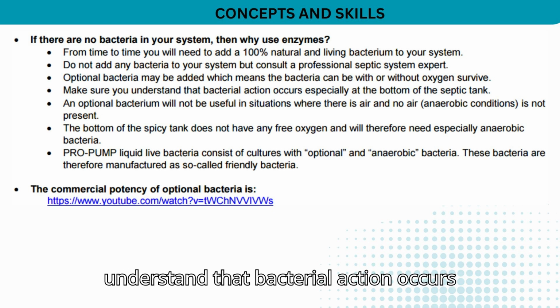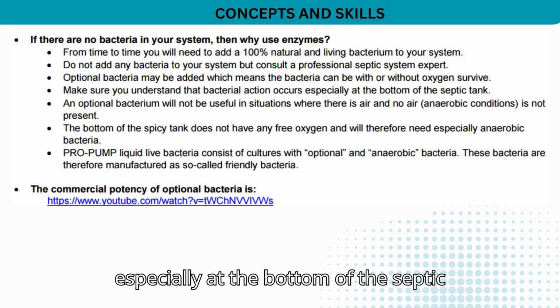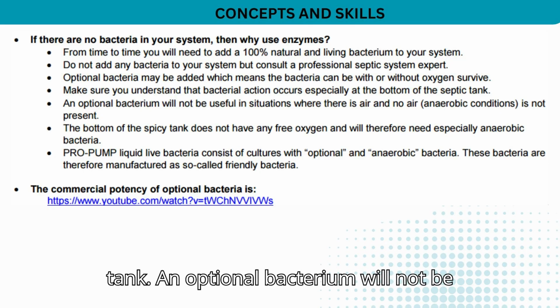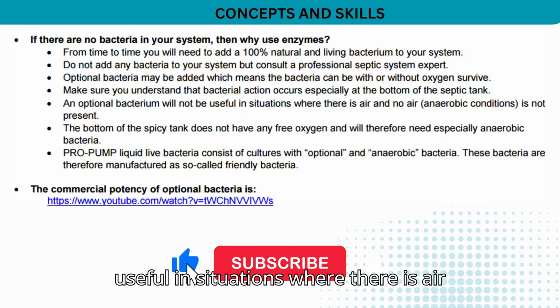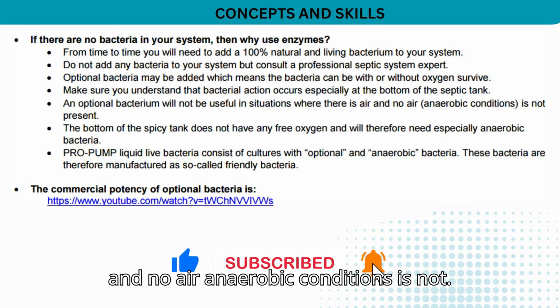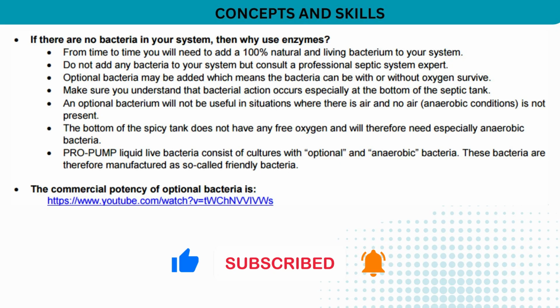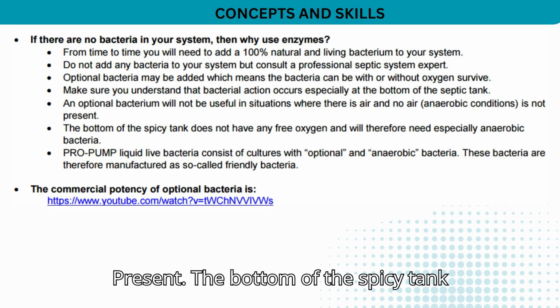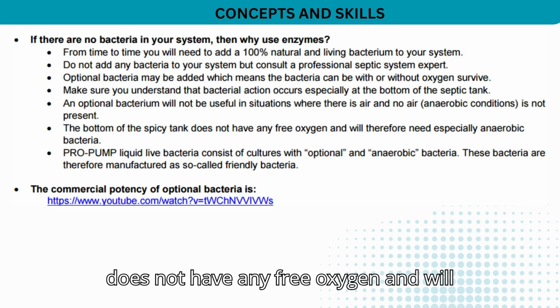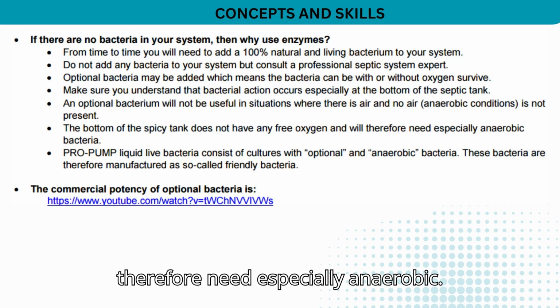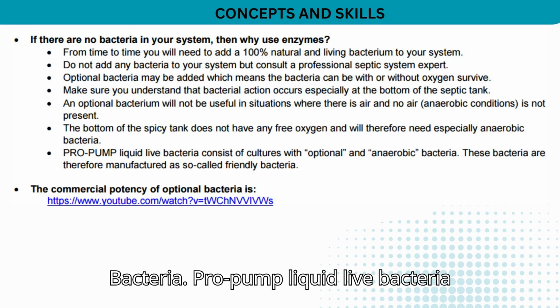Make sure you understand that bacterial action occurs especially at the bottom of the septic tank. An optional bacterium will not be useful in situations where anaerobic conditions are not present. The bottom of the septic tank does not have any free oxygen and will therefore need especially anaerobic bacteria.